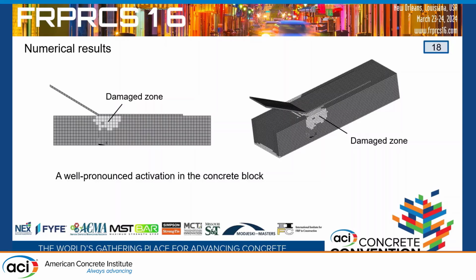Here in white gray you have damaged concrete. In the zones where you have white gray, for example, the elasticity modulus instead of 28,000 is 20,000. So we have degradation of the material properties. Okay.